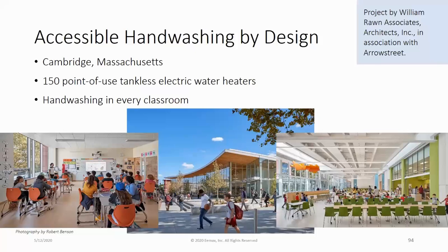They had geothermal for their HVAC, they had solar, they had radiant panels, and they used electric tankless water heaters throughout their facility for hand washing, janitorial requirements, and tepid water safety systems. So, electric kitchens, I mean, it truly was extremely well done. It supports the environment, it supports the neighborhood, achieved the right efficiency goals, promoted the right habits. And at the same time, it's a beautiful facility.